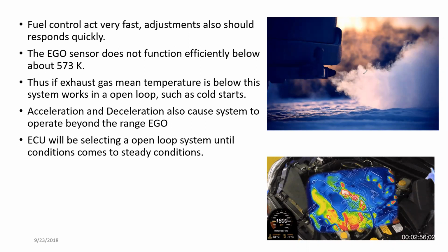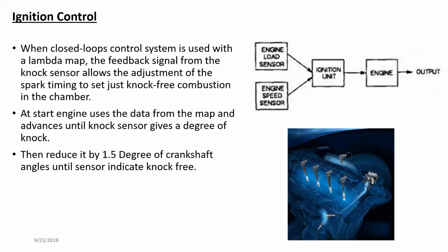While the fuel system is working on that, we have to look at the ignition system, which works parallel to the fuel system in order to maintain the combustion process. As we discussed in the previous modules, the engine load and vehicle speed dictate how much ignition advance and retard has to be done, so the ignition point is dictated by the engine speed and the engine load.